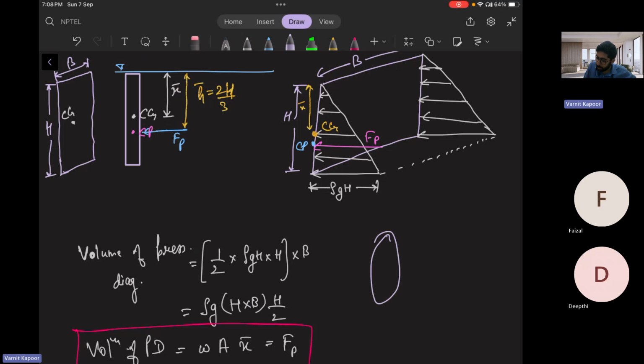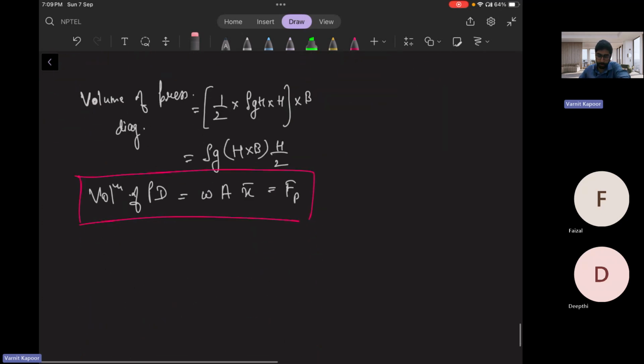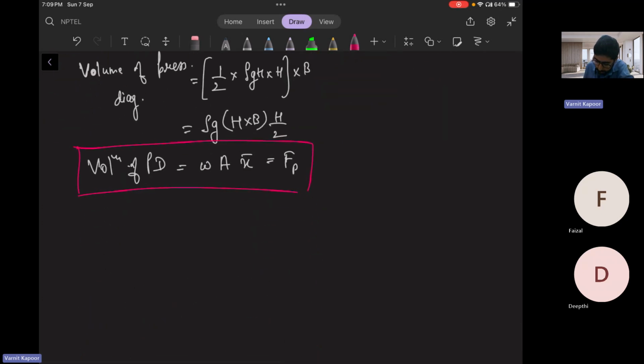At this radial position pressure will be there, at this radial position pressure will be there. It's not a continuous volume to get the value of the volume from. Even if you have a triangular plate as well. So that's why it is only applicable for rectangular flat surfaces, this pressure diagram technique. So I'll write here as a note.